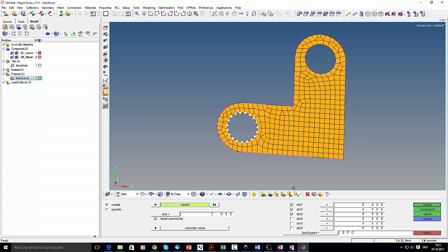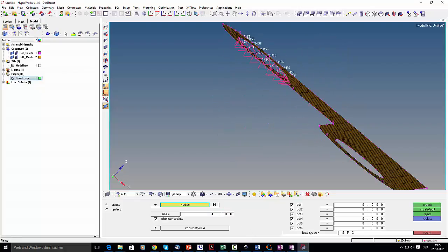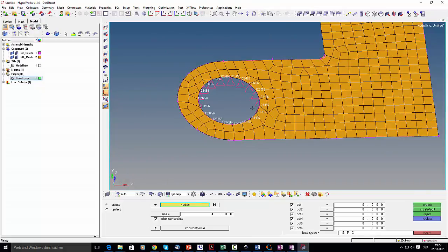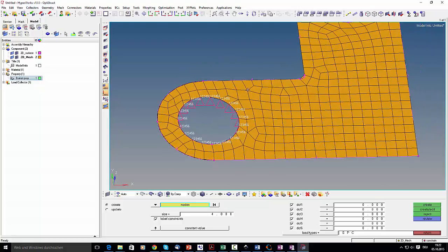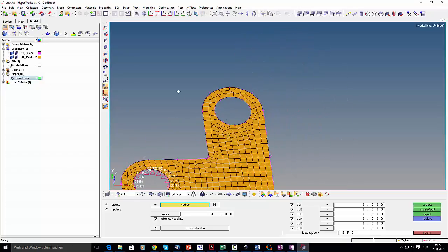there are different ways of select. In the tutorial it's also like degree of freedom 4, 5 and 6, but you don't need it because we couldn't hold it anyway in this direction, because the nodes, actually they are shells, are able to do it in some direction, so we click it on, we confirm it, and now you see I have to maybe increase the size, that you have this constraints of all directions and all moments, all rotations now on these nodes.